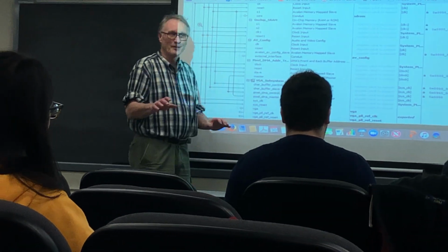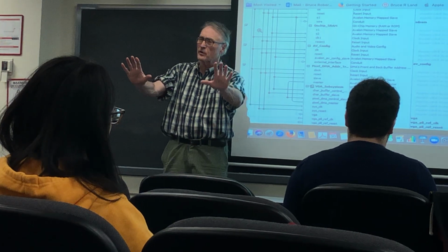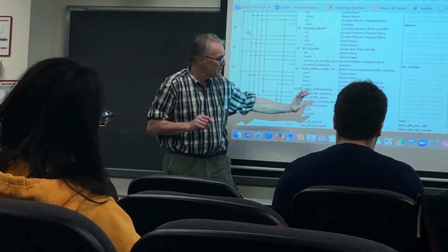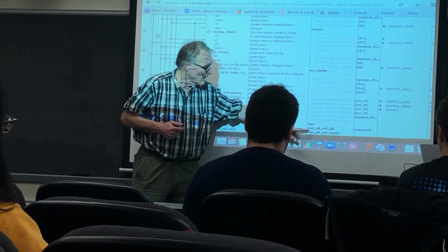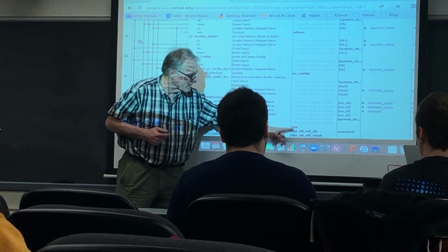Well, the answer is, not only is there this bus structure, which is internal to the module that's going to be generated, and you're never going to see that bus structure in your Verilog. There are going to be signals that you can export, in this case called VGA, VGA clock, clock, and reset.